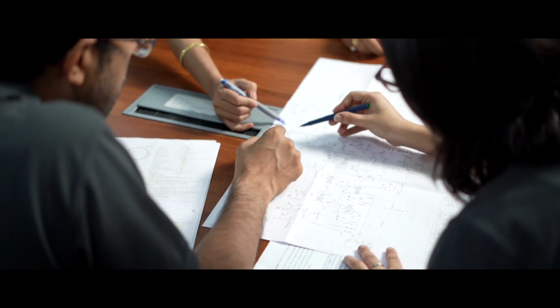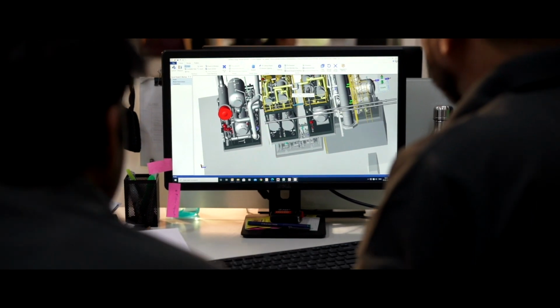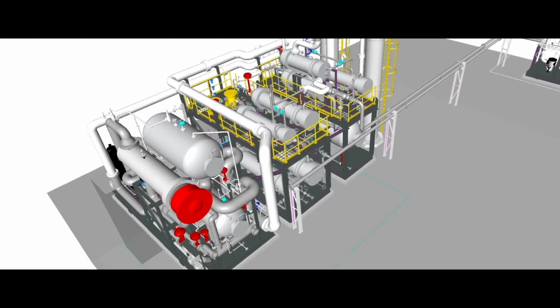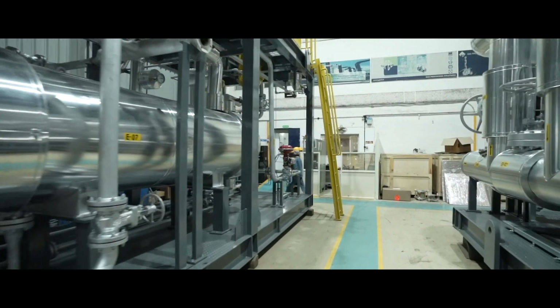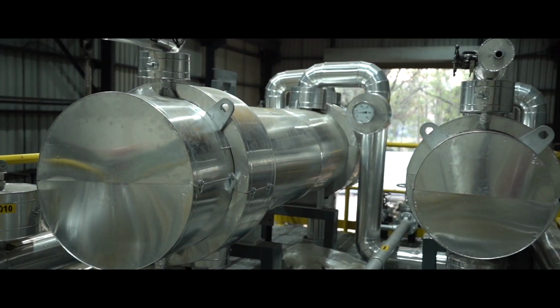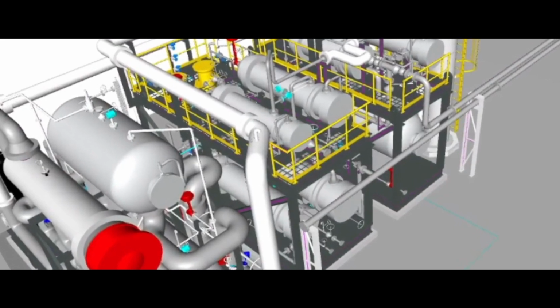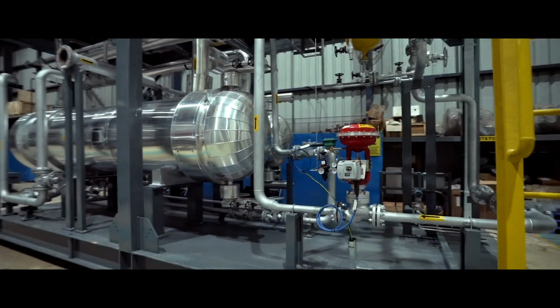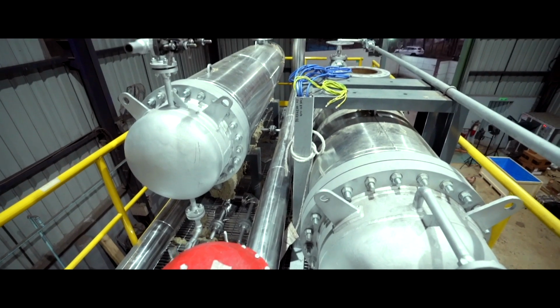In line with design concepts of modular process plants, process and utility flows are divided into various skids. There are 4 process skids and 2 utility skids. The feed and the product kerosene streams are integrated in the transfer skid. The feed kerosene flows through a duplex particulate filter and 2 recuperative heat exchangers in series, where the hot product liquid preheats the liquid going to the lead distillation tower. The 2 product streams are further cooled by 2 water-cooled heat exchangers.